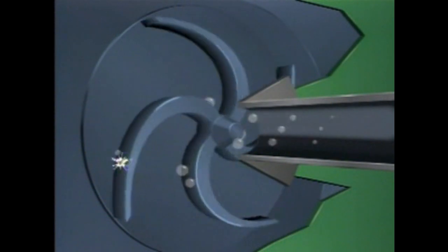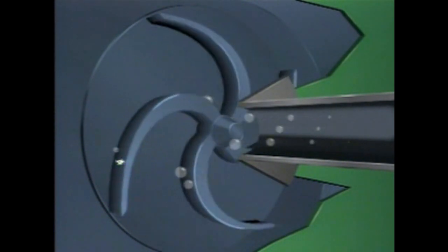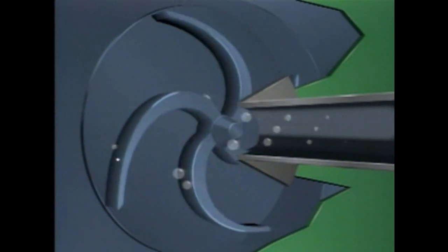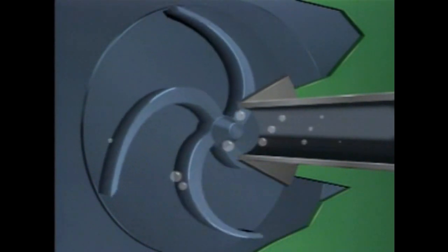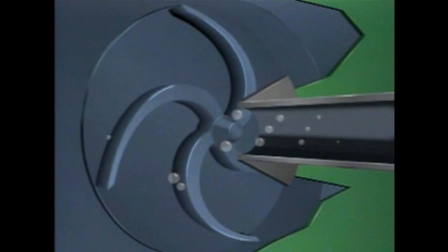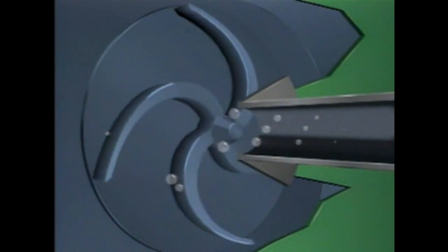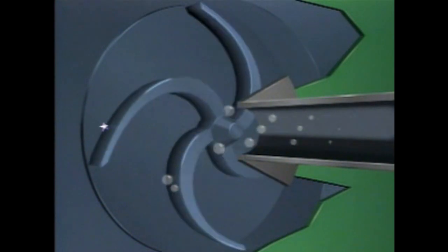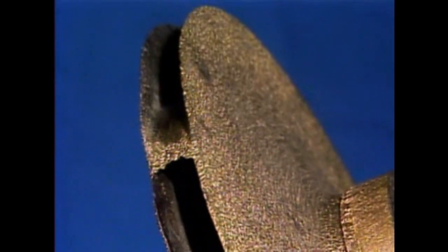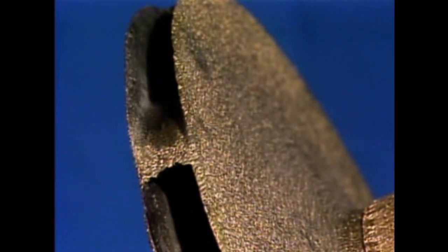As thousands of these bubbles travel toward the higher pressure areas in the pump, they are compressed until they can no longer withstand the pressure and collapse or implode violently. As liquid rushes in to fill the collapsing bubbles, it strikes the inside surfaces of the pump and gradually wears away pump material. The result is a sandblasting effect on internal pump components, such as this impeller. This kind of damage decreases the performance of the pump.